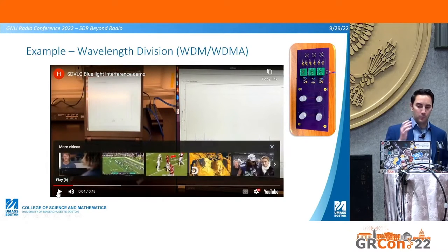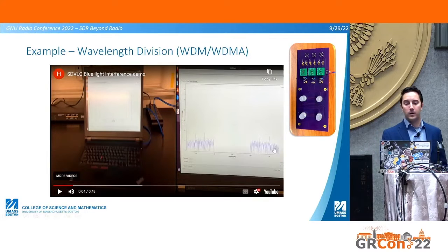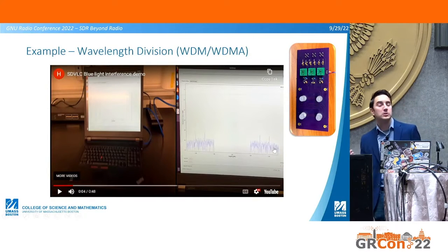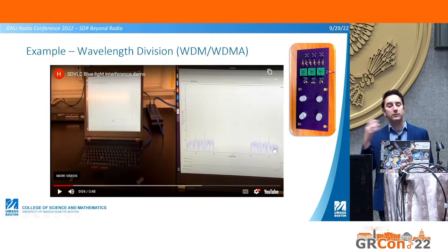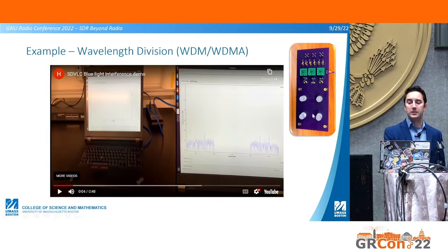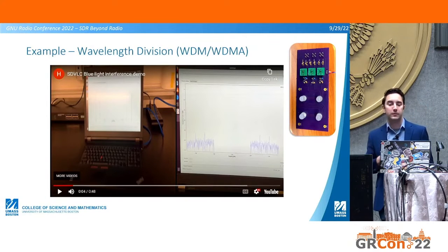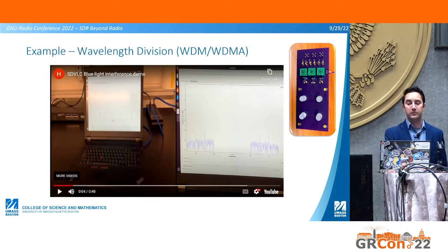So one of the last things I mentioned there was we have this option of doing color channel selection. If we put different optical filters on our receiver, we can pick up different signals from different color light emitters. Each one of these LEDs is an RGB LED, so we can control a red, blue, or green signal. We can do this for multiplexing to send 3 separate transmissions simultaneously, or we can send a different color on different channels intended for different receivers. What we'll show here is using this for interference mitigation.